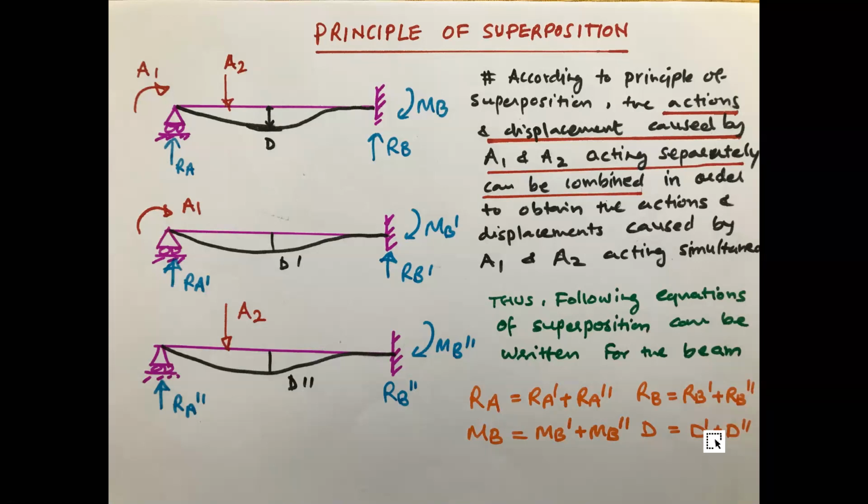It might happen in earthquake analysis of structures also, where there are inertial forces. There you can see the non-linear behavior, a non-linear relation between the force and the deflection. So when you calculate, the forces or deflections have some powers mathematically. In that case, we cannot use the superposition principle. It is only for linear structures, that you have to keep in mind.